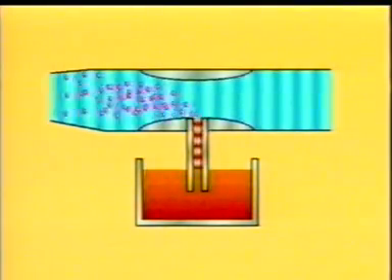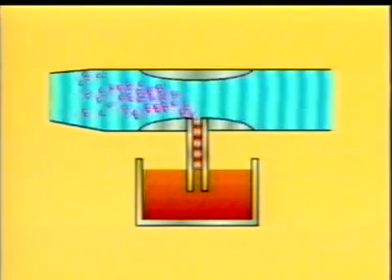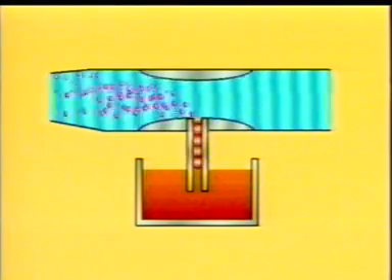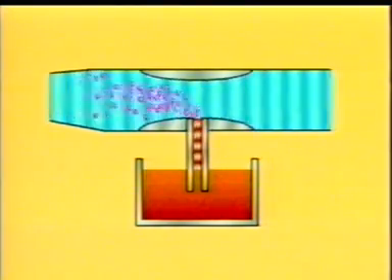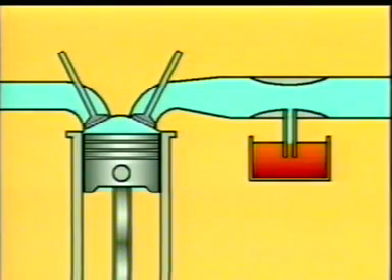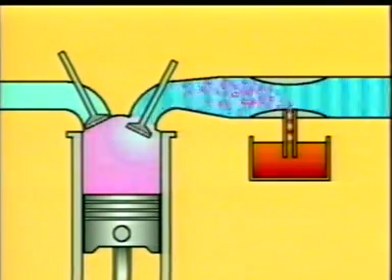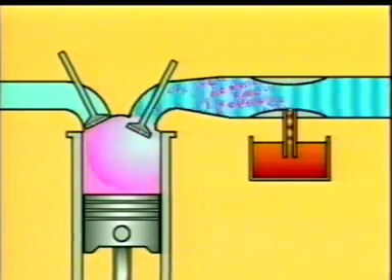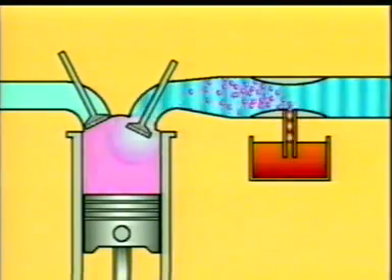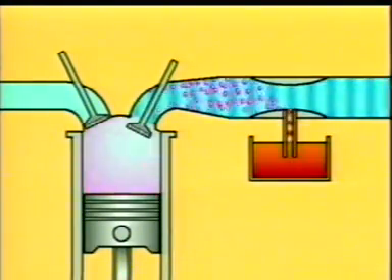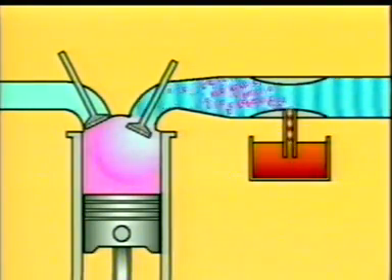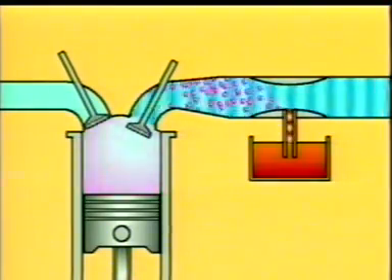The carburetor uses this Venturi to draw in fuel and turn it into a spray. When the piston moves downward during the engine intake process, air comes flowing into the cylinder. At this point, negative pressure is created at the Venturi so that fuel is drawn into the carburetor, turned into a spray, and mixed with the air.